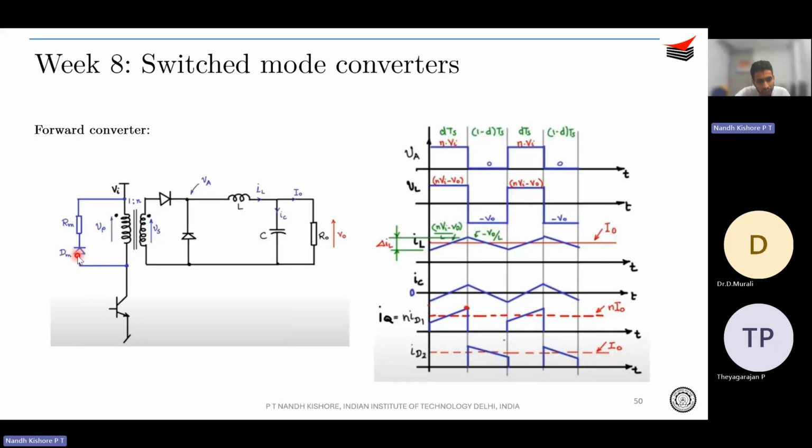Okay, so this diode will ensure that there is only unidirectional current flow, that is only in the reverse direction. Correct. So the stored energy in this inductor will dissipate through RM. Okay, right. So again, you went through what is the switch rating and all. That is the current through IQ and the current through the diodes and all, right?